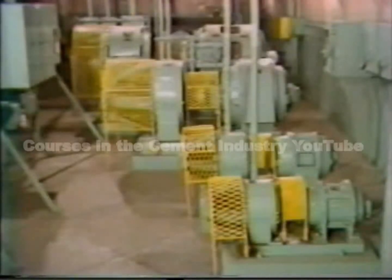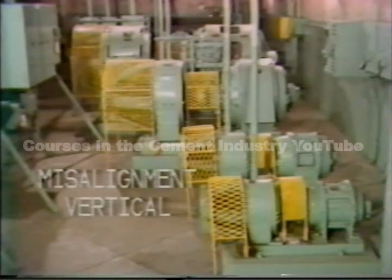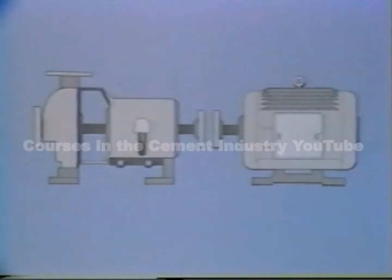Now that we know that two types of alignment exist, let's go a little deeper. Misalignment is measured in two planes, vertical and horizontal. Let's take them one at a time while I explain the difference. The drawing we're looking at shows the pump and motor from a side view. From this point, any misalignment found would be in the vertical plane. Let me show you what I mean.